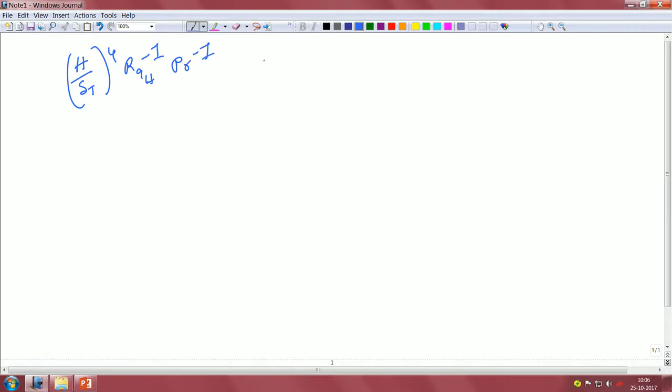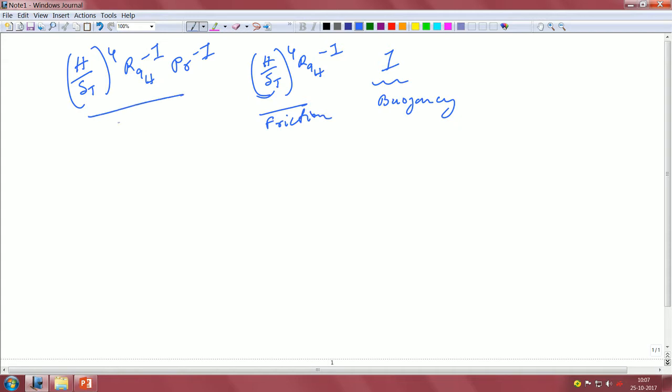Then there was the friction term, and of course, this is buoyancy. So, this was basically our buoyancy term, right. This was the friction or the viscous term, and this was the inertia, right. So, depending on the value of your Prandtl number, we can have different types of scenarios. So, let us take the high Prandtl number fluid, which means its Prandtl number is much greater than 1.